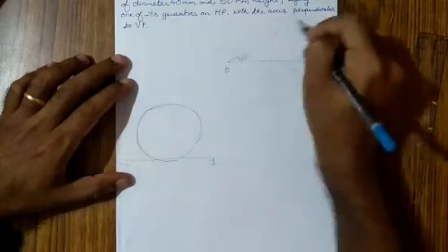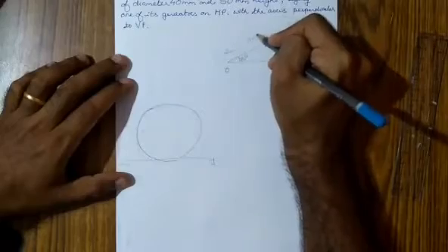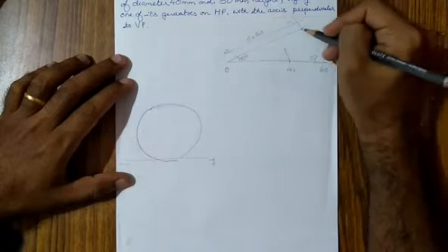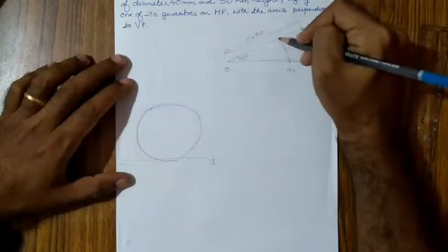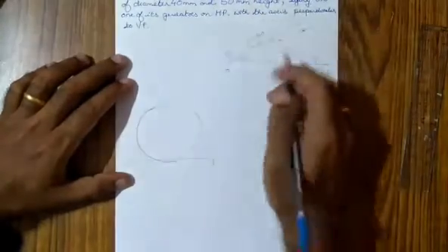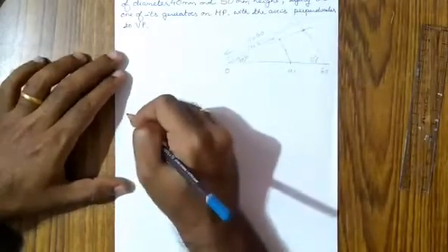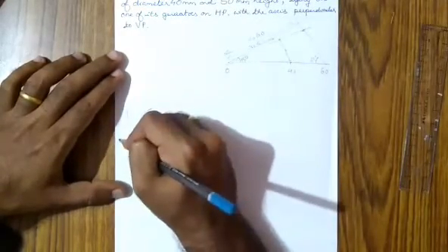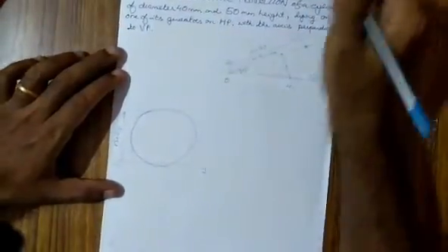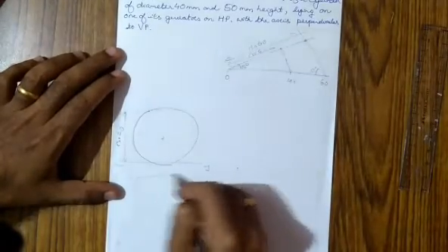This is going to be your isometric. Based on the true 60, this is your isometric 60 length, and based on the true 40, you draw a line through 40 parallel to this edge. This small length is going to be your isometric 40. You take this length as the diameter. So the solid is drawn with a diameter of isometric 40, and this is going to be the top view of the solid.